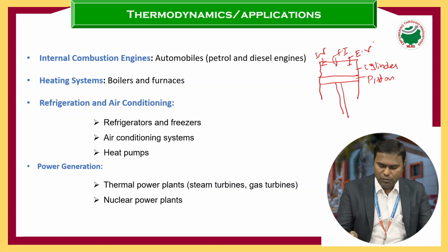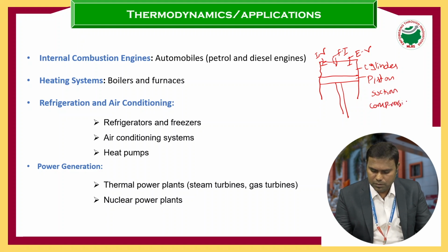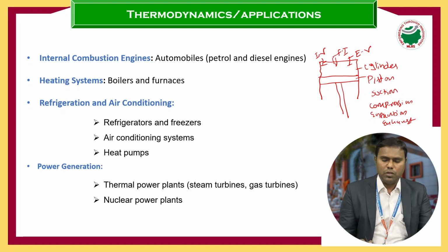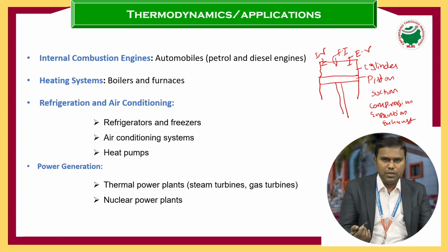We have 4 strokes: suction stroke, compression stroke, expansion stroke, and exhaust stroke. In the suction stroke, if it is a diesel engine, air enters the engine cylinder, and in the compression stroke, air is compressed.